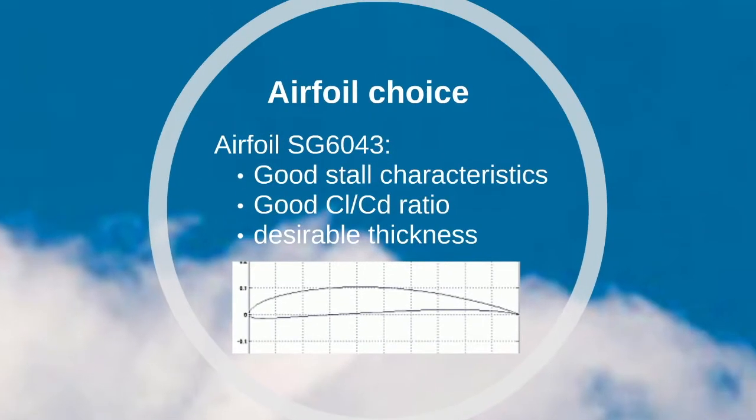We want to maximize the rotor torque at our design TSR. This would be obtained by maximizing the CL over CD ratio. Using the Airfoil Tools database, we then shortlisted the different types of airfoils which might be suitable for our design. In the end, we chose airfoil S6063, as it presented a good L over D ratio, good stall characteristics, and a desirable thickness.